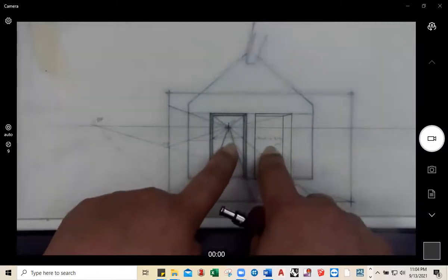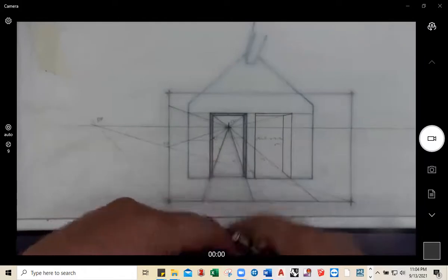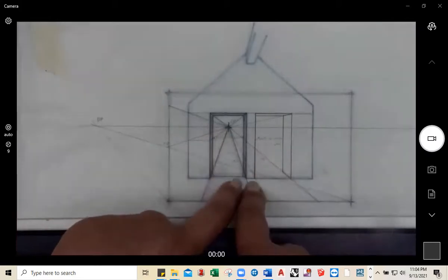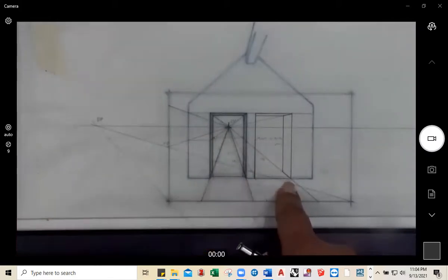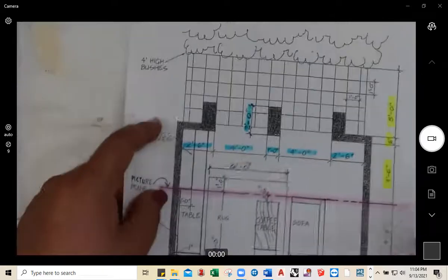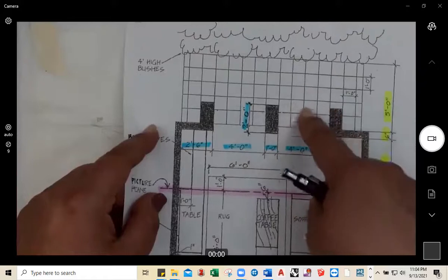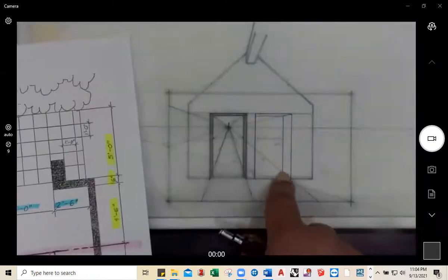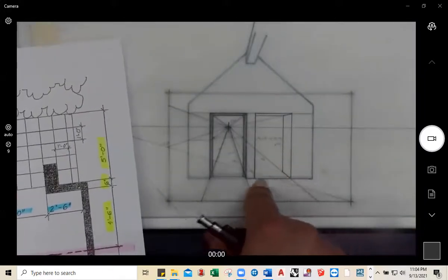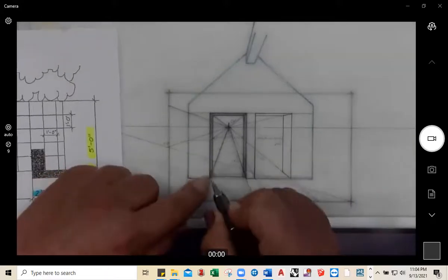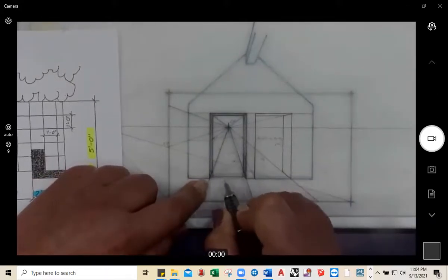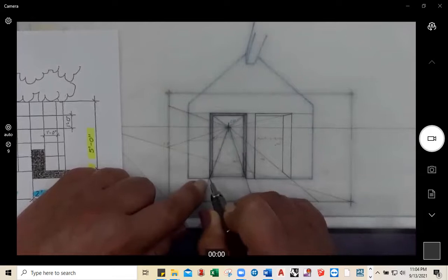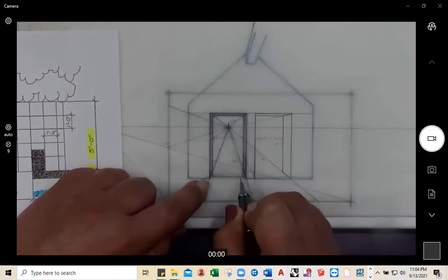The tile, remember, the last 5 rows of the grid, those are the tiles. It's not going to go all the way to this edge because remember, if we take a look at where the tiles begin, notice, 1, 2, 3, 4, 5, and then where the wall is, see how there's a little gap between them? There's a 6-inch gap. So the tiles do not go all the way to the bottom of this back wall. They actually go in a little bit, those 6 inches. That's why you see this here, right? So this is where the grid for the last 5 ends. It goes in 6 inches.